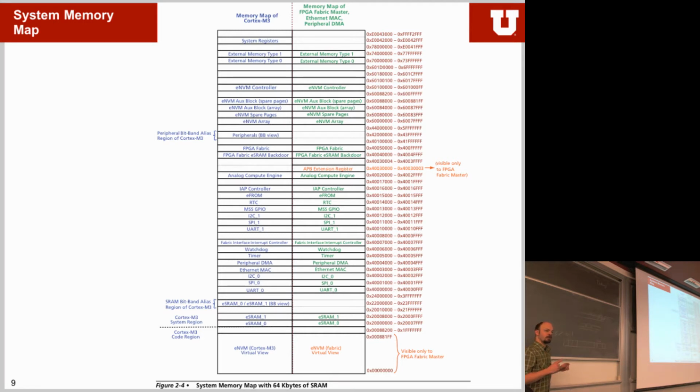So the problem is you can't just write a one left-shifted by 30 into this register, right? Because what would happen is you would set all these other bits to 0, and that bit to 1. So you just changed the output of your I/O lines. What if you don't want to do that?